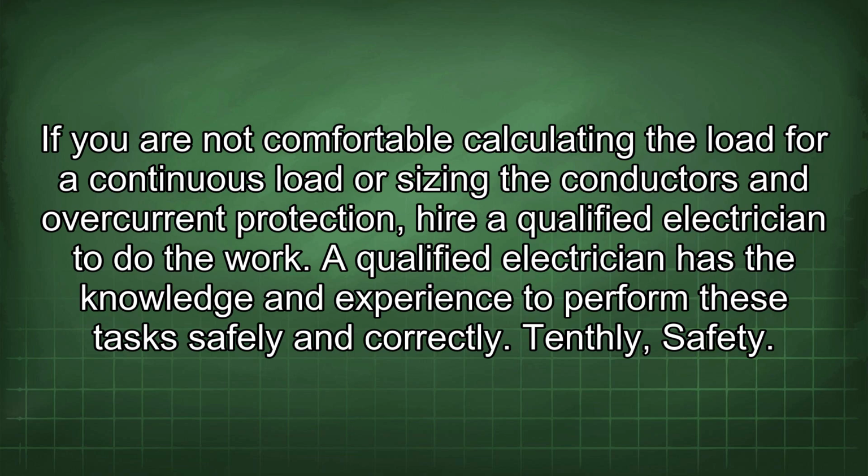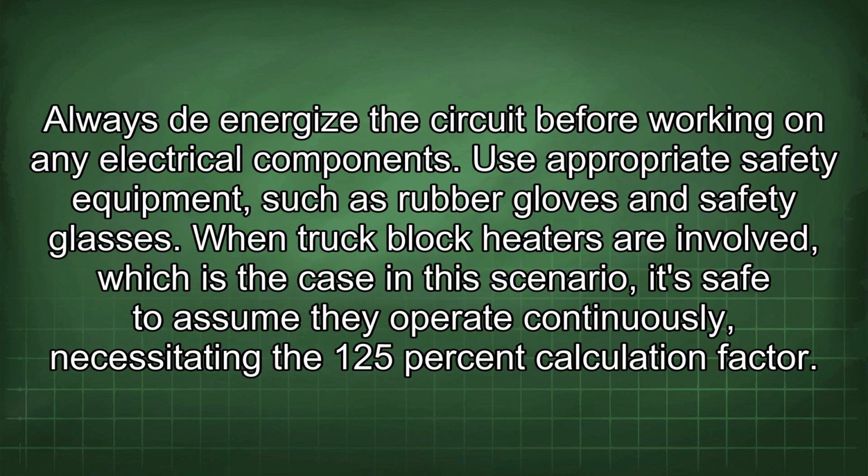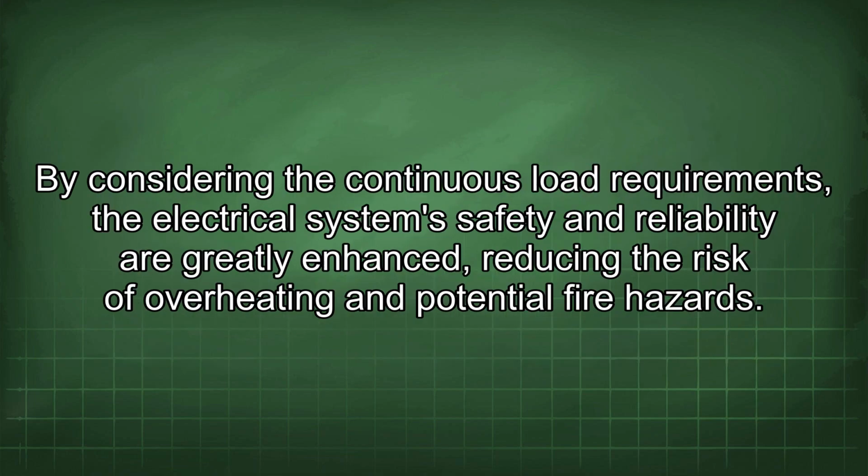Tenthly, safety. Always de-energize the circuit before working on any electrical components. Use appropriate safety equipment, such as rubber gloves and safety glasses. When truck block heaters are involved, which is the case in this scenario, it's safe to assume they operate continuously, necessitating the 125% calculation factor. By considering the continuous load requirements, the electrical system's safety and reliability are greatly enhanced, reducing the risk of overheating and potential fire hazards.